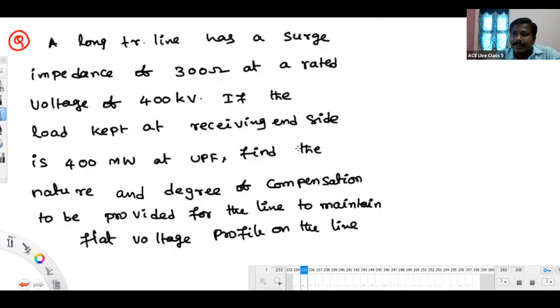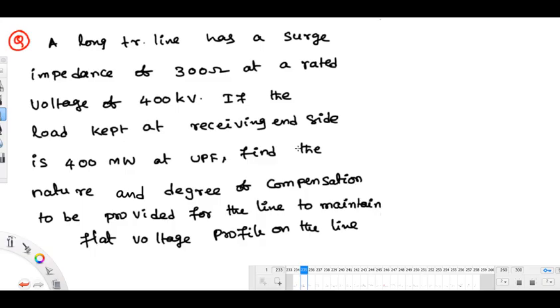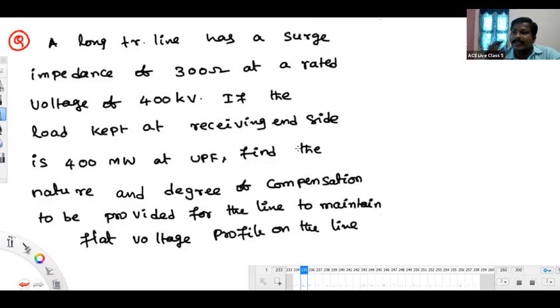A bulk number, right? 130 kV lines, if you think outside. Each and every 130 kV by 33 kV substation will get 2 or 3 lines. So the number of 130 kV and 33 kV lines is very large, and providing compensation is very difficult. So you try to keep your loading close to SIL for those lines, such that VR will be close to VS, reducing the requirement of compensation equipment.